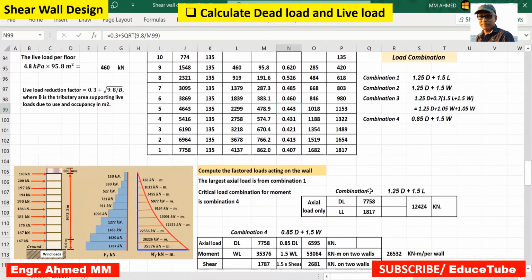So here there are important things we need to understand. Compute the factored load acting on the wall. We know dead load, we know live loads. Now compute the factored loads acting on the wall. So there are 4 combinations: dead load, live load, dead load, wind load, and here also dead load, live load, wind loads combination. You can read it, combination 4, this one. But we will use these two combinations.